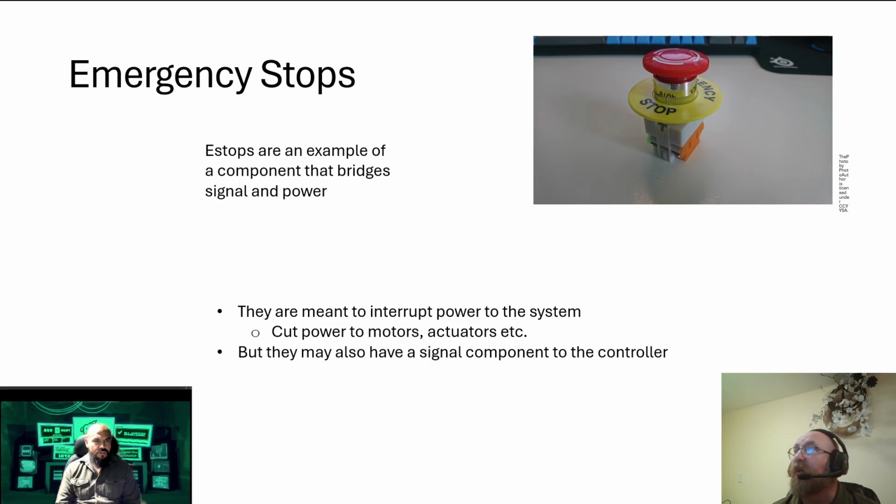You definitely don't want that programmed into your PLC code, where somebody might change what an e-stop does, and then that e-stop is no longer an e-stop. And if you do have the PLC managing that e-stop functionality, there are rules around that.